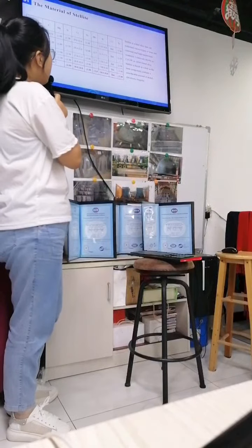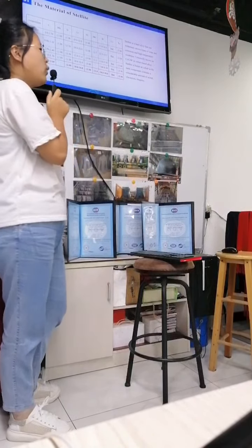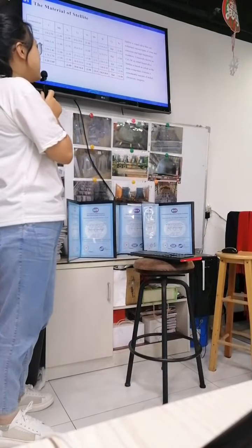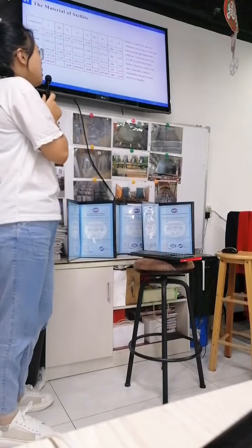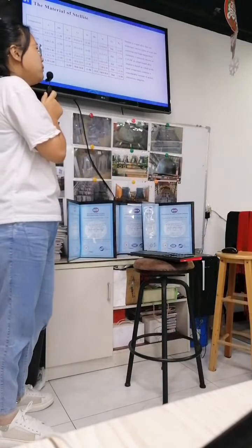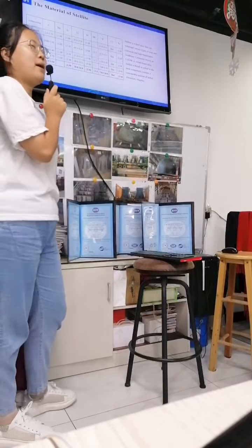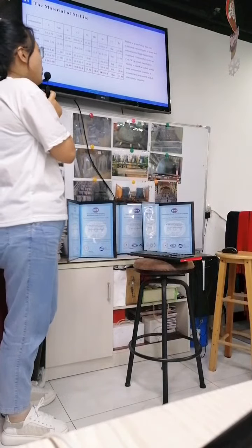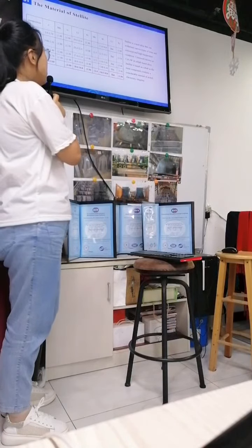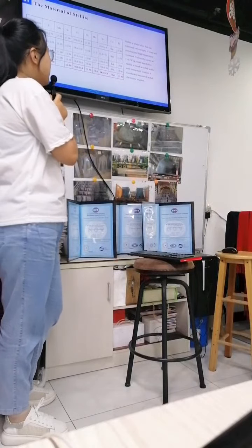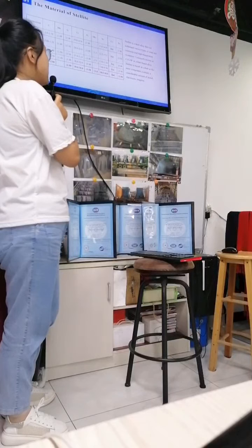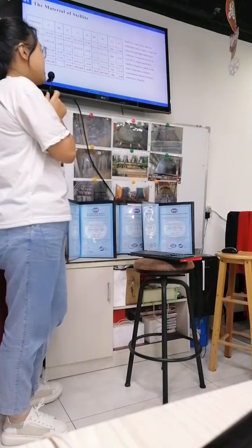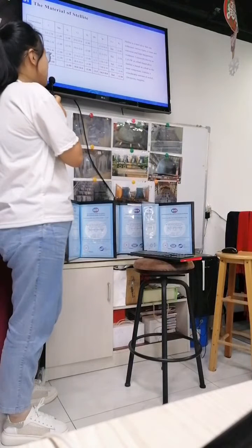C9-4. For carbon is 0.8 to 1.2%. For chromium is 28 to 32%. For tungsten is 1.5 to 15.5%, and the cobalt is balanced. C9-6. For carbon is 0.9 to 1.4%. For chromium is 27 to 31%. For tungsten is 3.5 to 5.5%, and the cobalt is balanced.